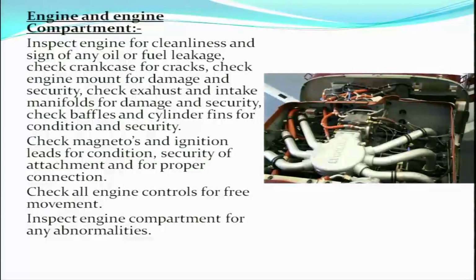So in the engine compartment, the general cleanliness has to be checked. You need to check for any leakage of oil or fuel, whether there are any cracks in the crankcase. We need to check the engine mounts for any damage, the engine mounts have to be secured. We need to check the exhaust manifold and the intake manifolds for any damage and security. The baffles and the cylinder cooling fins are also to be checked for condition and security.